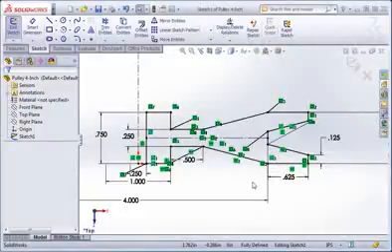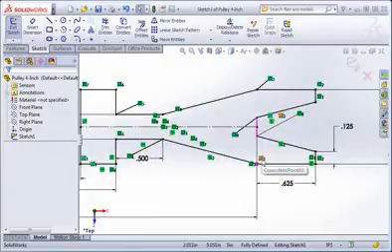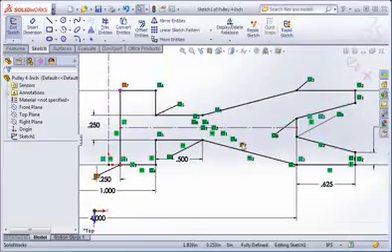Now that we've mirrored the geometry, we've created a closed loop profile that has new relations. The coincident 3 relations are still there, but notice that the line is twice as long as it was before. It used to end on the construction line, and now it extends to the mirrored point. This is a symmetric relation named symmetric 1. If you highlight it, you can see that it contains 2 points so that they're symmetric about the construction line. In fact, each symmetric relation on the construction line constrains the location of 2 points.